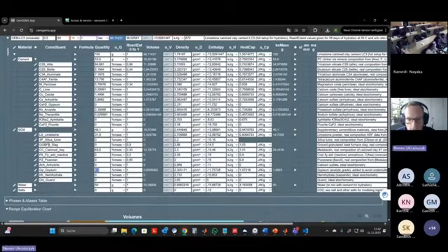And yeah, you can add slag, you can add silica fume, calcined clays. This is 63% of calcined clay inside limestone. And you can add fly ash. Yeah, I don't see any ash, but I would use silica fume for ash, and then just change the kinetics and maybe also the degree of reaction. Here they put it as fully reacting, which is also never the case. It cannot react fully. It always has a limited extent.